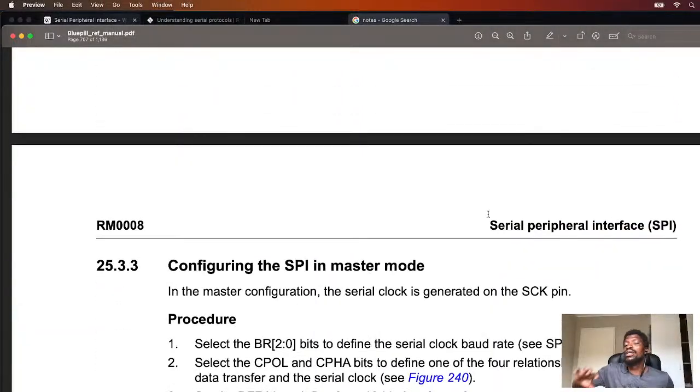So basically you can get a clock from somewhere and divide it. I think the least you can divide it by is 2, so you'll have to divide it by something. You won't be able to just use your full clock. And this is for STM32 devices at the moment. There could be an STM32 device that does not need this.